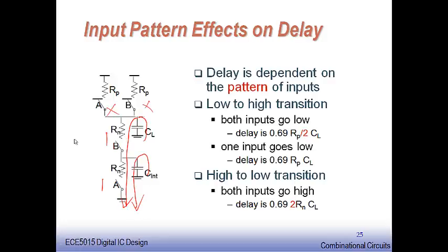Now this condition I will impose. Previously I was having a 0 state for this switch B transistor, and it now is going towards logic 1. In such a case, previously because this was 0, this device was off and there is no chance that there will be any charge here on this CINT.